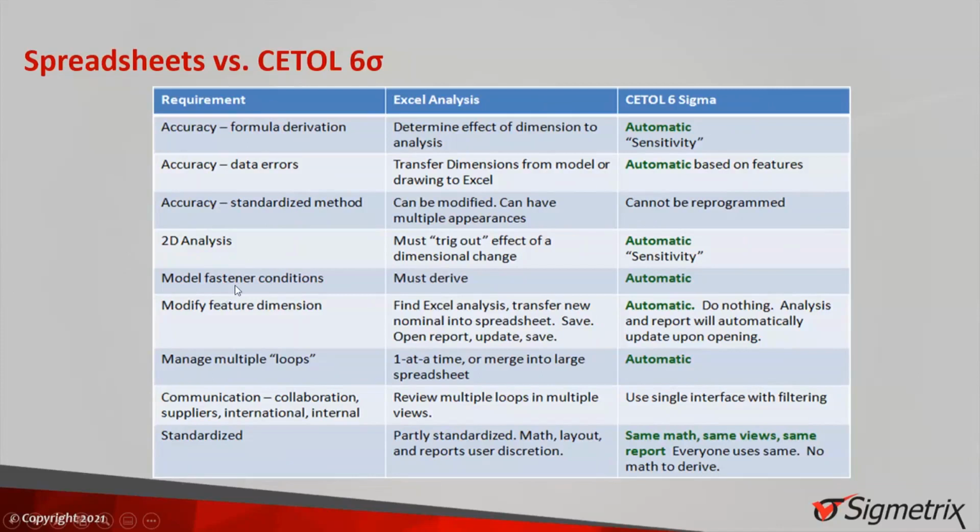And okay, about the fastener conditions, you may consider interference fit or clearance fit, even the transition fit. But in CETOL, it is automatically considered. So also it will advise you if you have some interferences in the fastener, you will get some message in this tool.